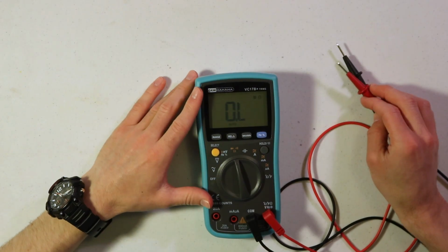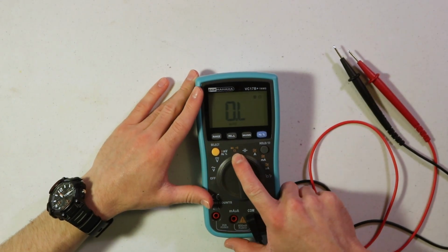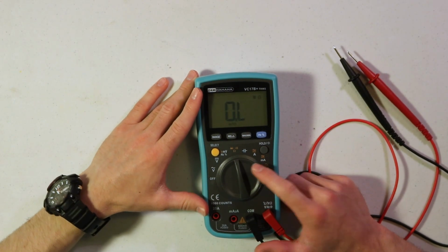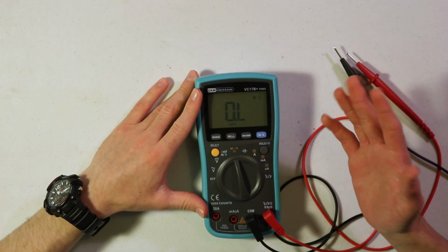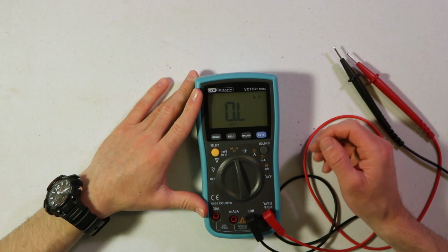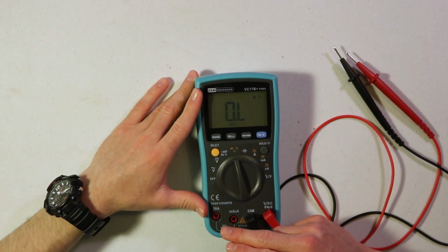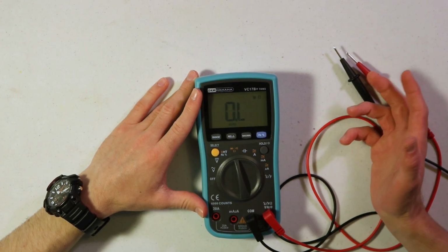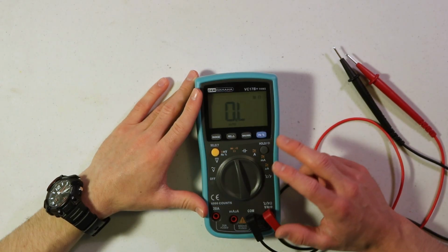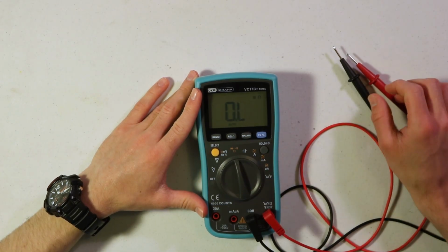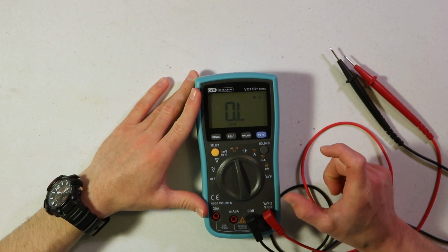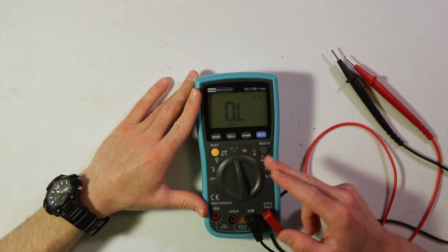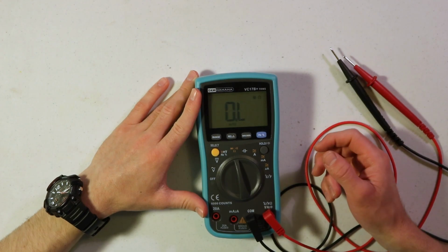If your multimeter is not auto-ranging like this, I only have one setting for measuring resistance, then you would just select the appropriate range. If you're measuring, say, 500 ohms, then you wouldn't want to set it on the 200 ohm range. You'd maybe want to set it on the 2 kilo ohm range or something like that. So just make sure you select the appropriate range. Always go as small as you can with the range so that it has the highest precision. But if you have it too far, then it's not going to show up with anything.